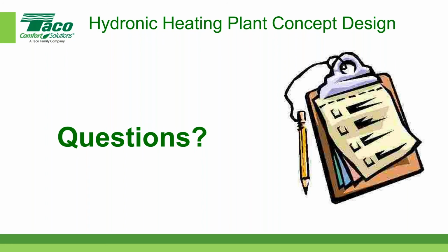However, with every decision like that, there are pros and cons. If I put the expansion tank at the top of the building and there are no other major pieces of mechanical equipment, I'd have to have enough structure in the building to accommodate the weight of the expansion tank if it became waterlogged. I don't know the exact size, but let's say you had around a 500-gallon expansion tank. If it was a bladder style tank, or say a full acceptance tank, it could become waterlogged and the 500 gallons would fill up 100%. We know that water weighs about 8.33 pounds per gallon, and at 500 gallons that'd be about 4,000 pounds. So you'd have to carry that weight of 4,000 pounds in the structure of the building. The tank gets smaller, but you may have a penalty of structural components to accommodate the tank at the top of the building. Next question.